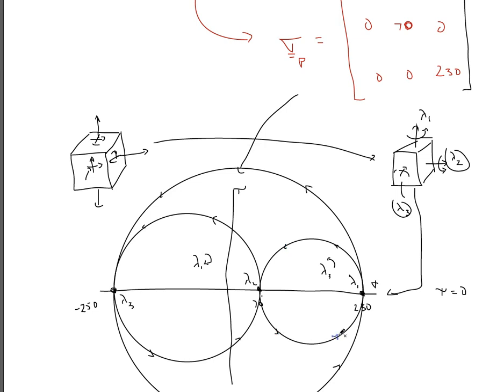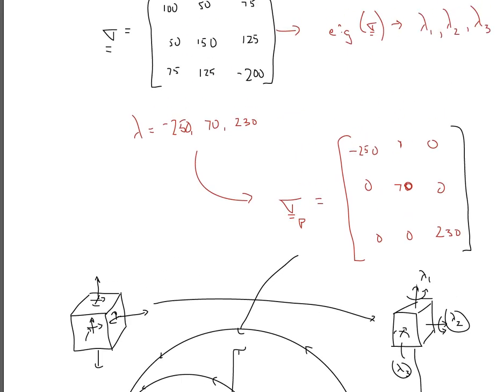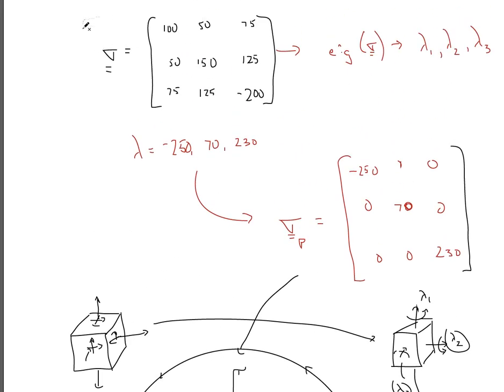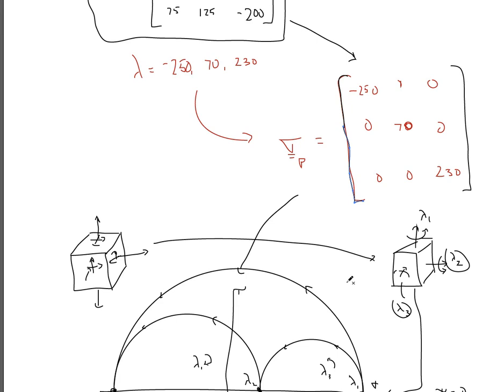So essentially, what we have just derived is all the internal stresses that can occur within a material based upon its 3D architecture. We did it with 2D before. Now we've done it for 3D. And this is where the stress tensor ends up becoming incredibly powerful, because by creating this tensor right here, we can then convert it into the principal stresses, and those principal stresses then tell us every internal stress that can occur within the given material for different rotations.